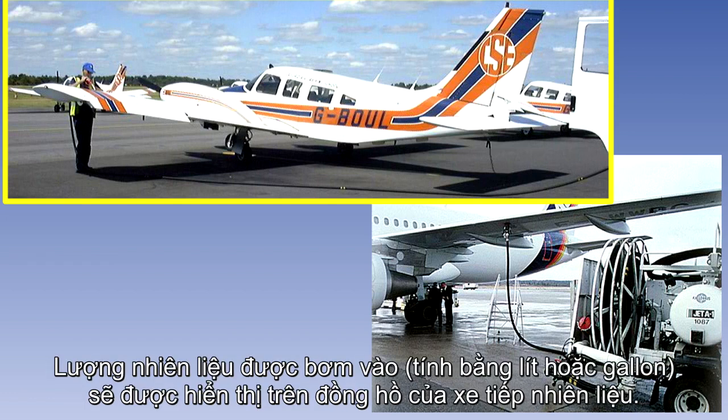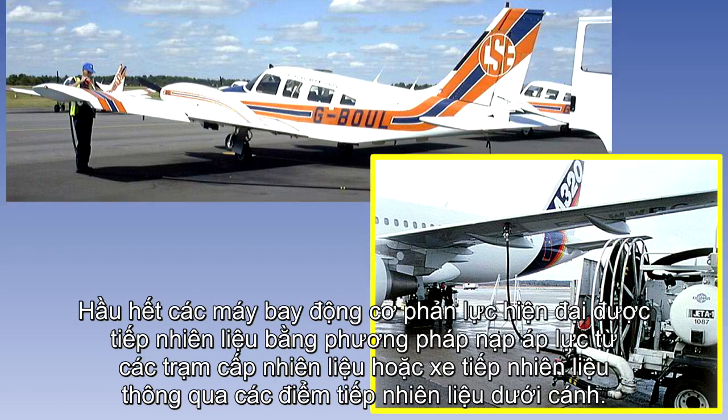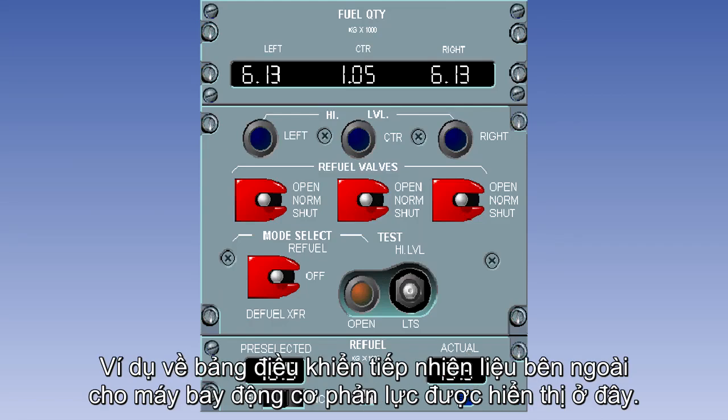This is known as the overwing method. The quantity of fuel delivered in litres or gallons is indicated on a gauge on the delivery vehicle. Practically all modern jet-engined aircraft are pressure refueled from hydrants or delivery vehicles through underwing refuel and defuel coupling points. The operation is controlled from a single external refuel control panel.